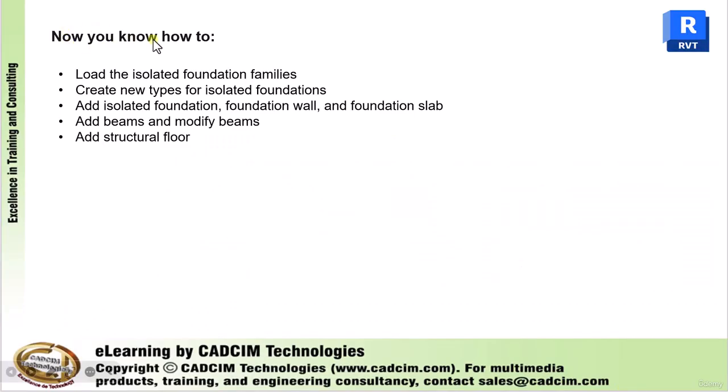Finally, now you know how to load the isolated foundation families, create new types for isolated foundations, add isolated foundation, foundation wall and foundation slab, then add beams and modify beams, and add structural floor.